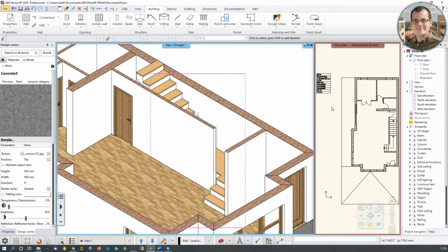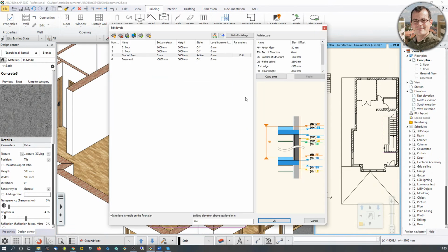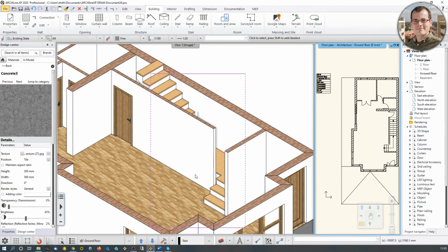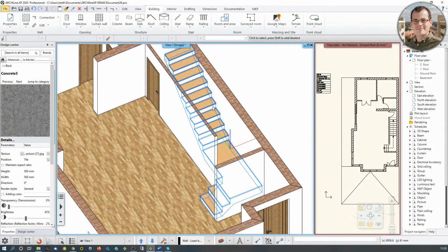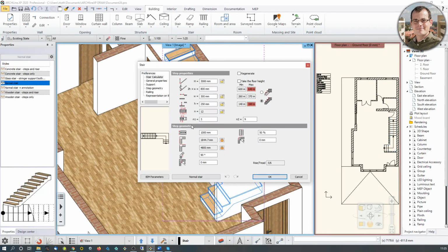The software comes with a floor structure. Now, when you create a building, by default, you are going to have 4 different levels: basement, ground floor, first and second floor. This you can fine tune, and also you can fine tune the height as well. Yes, that's all fine, but how does this thing turn into a nice staircase like that one? So for that I have to go back to the stairs properties and keep on talking about what I can fine tune. So hit the stairs, and first I have already talked about the 3000 millimeters, that's fine.